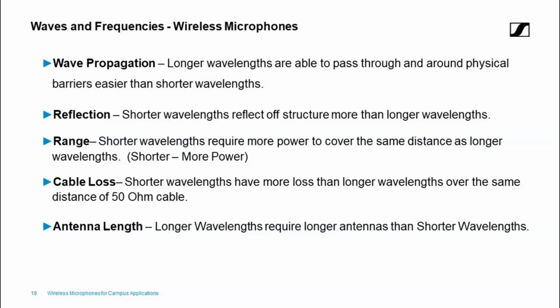If I'm going to cover a football stadium at a college and I want to have a ref mic or have a reporter's mic down on the field, I want to have a longer wavelength, a lower frequency, because I don't have to push it as far with less power as I would with a higher frequency or shorter wavelength. The same applies with cable loss.